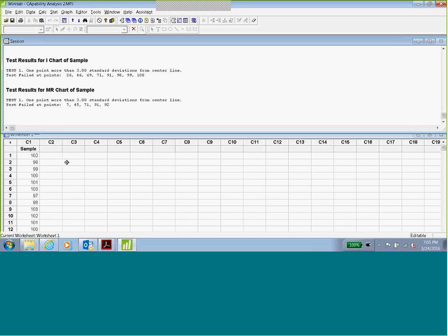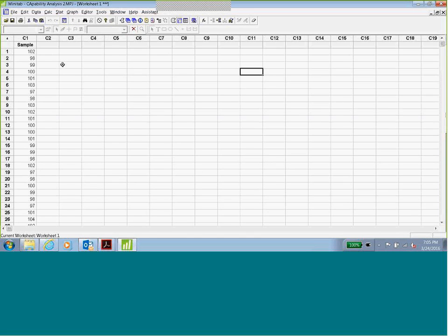And the second study is process potential, which uses consecutive samples. Give the results in one column, go and select the process capability 6-pack, have your specification limits and target, and get a CPK value, in one case greater than 1 and in another CPK value less than 1.